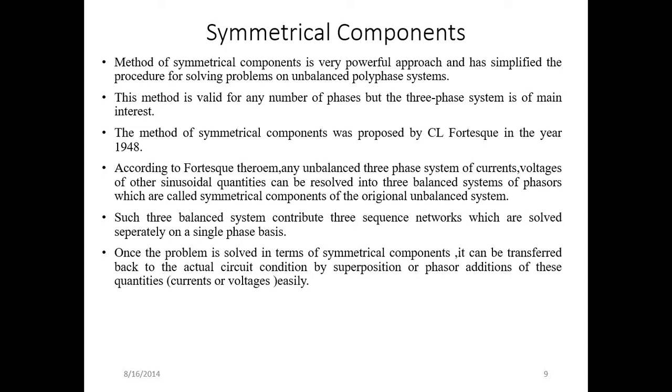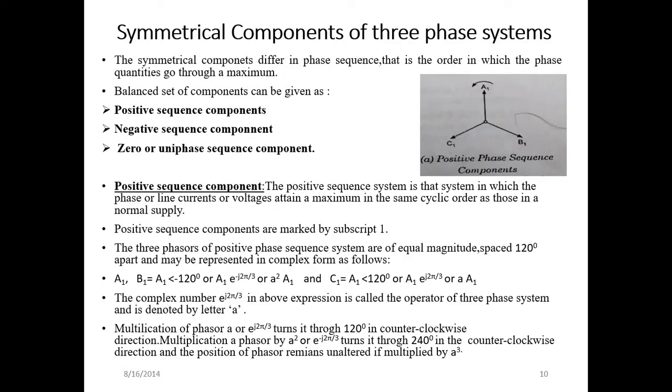Once the problem is solved in terms of the symmetrical components, it can be transferred back to the actual circuit condition by superposition or phasor addition of these quantities. Thus, in short, the symmetrical component helps to convert an unbalanced system into a balanced one for analysis purposes, and once analysis is done, it is converted back into the original one.